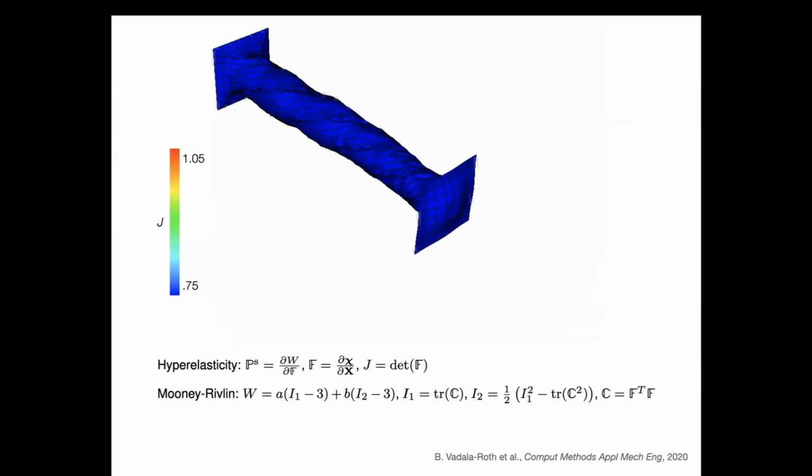This is a mechanics setup that is great if you ensure that the Lagrangian velocity field is exactly divergence free. If you have an exactly incompressible solid mechanics formulation, then this is what you would want to use for your energy, and you would use this setup to compute your stresses.